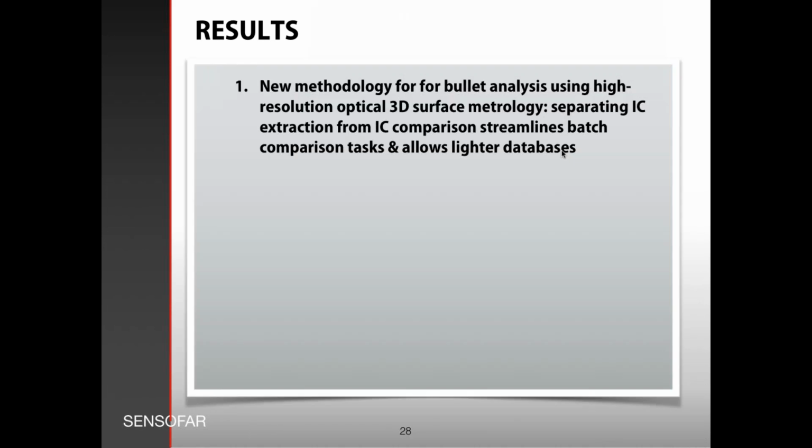Finally, I want to summarize what we have been presenting. We have created a new methodology for bullet analysis using high-resolution optical 3D surface metrology. It consists of separating the IC extraction step from the IC comparison, which streamlines the batch comparisons and allows a lighter database.